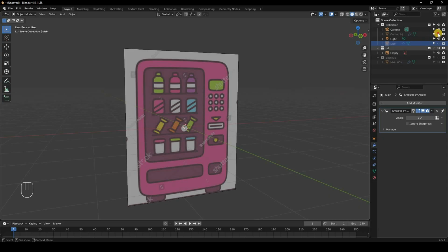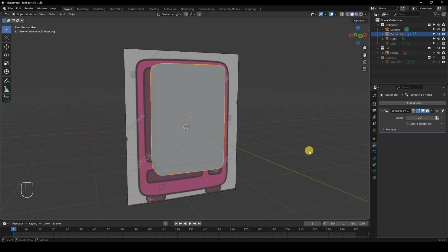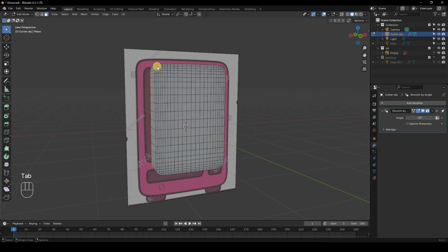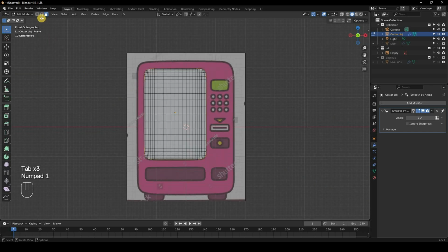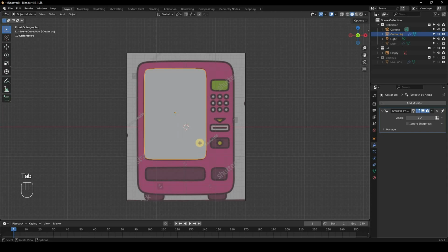And remember, with our cutter object, you're not going to just start scaling it on the z-axis or something like that, because if you do that, these corner edges will also be scaled and the shape will be deformed. And again, you can obviously use the same technique I showed you before, Shift and click, Shift Alt, and start selecting these edges and vertices that are unimportant, and dissolve them, or you can just create a new cutter object.